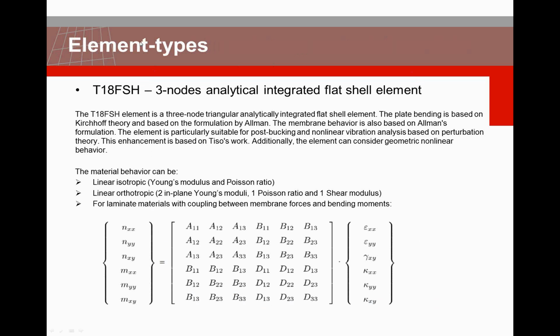When we look to new element types, there are not so many new element types coming available in Diana 9.5, but we have already many. But we have added in Diana 9.5 a new 3-node analytical integrated flat shell element, which is an analytically integrated element. So we have only one integration point in the plane of surfaces, and the constitutive model is defined in terms of